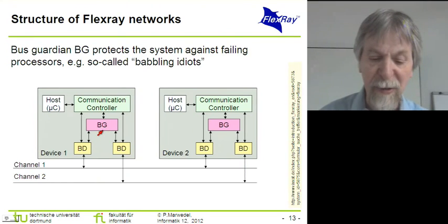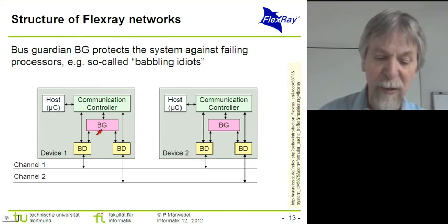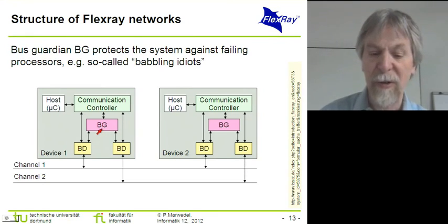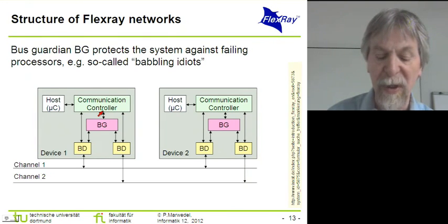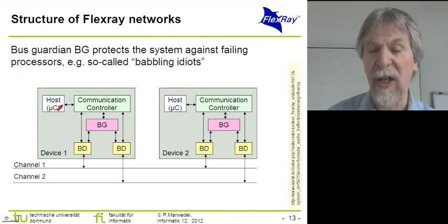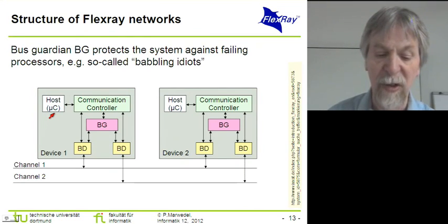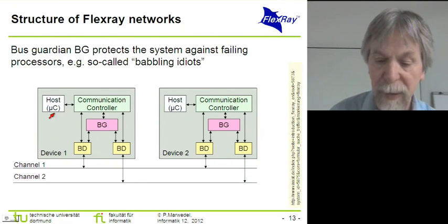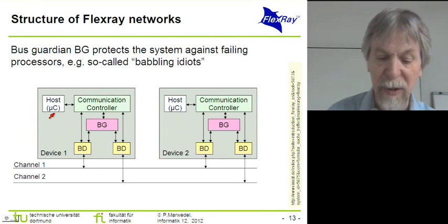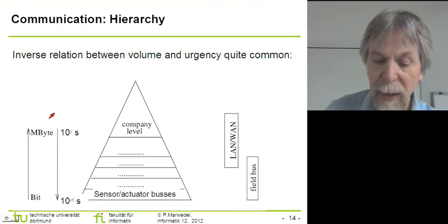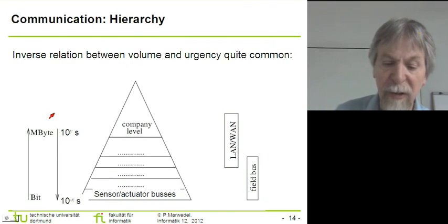Now, FlexRay systems have an advantage in this case, because for FlexRay systems we have a so-called bus guardian which is supposed to protect the communication controller against these babbling idiots, so that this communication noise doesn't really reach the communication controller, and also, of course, it doesn't reach the microcontroller that is hosting a particular device. So in this way, we are caring about the overall reliability and dependability of the system. So that concludes the presentation of FlexRay.